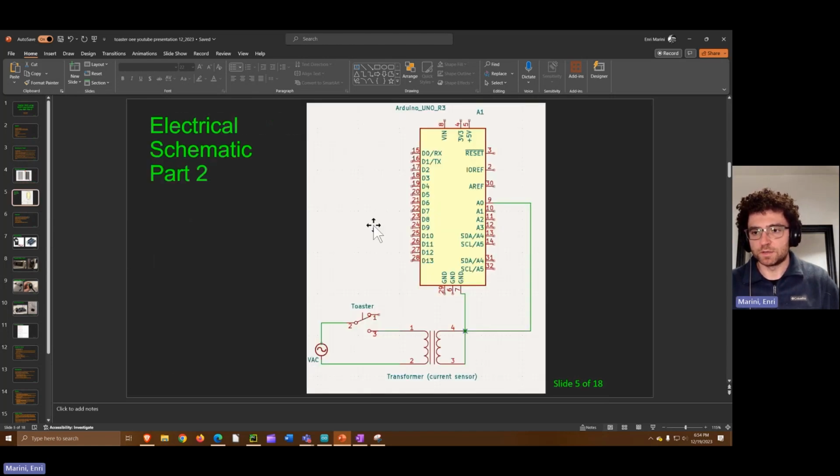So this is a schematic of the setup. You have your wall power, 120 volt AC, since I'm in the States. You have your toaster, and essentially it's just a switch where the front of the dial, and you'll see photos in a little bit, you turn clockwise and it's timed. That switch will stay on until eventually a spring releases it and disengages after a certain amount of time. That time is based on a set of physical properties of the spring that's holding the knob together, and that's how the knob eventually releases to then allow for an open circuit.